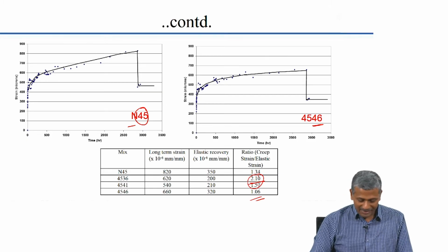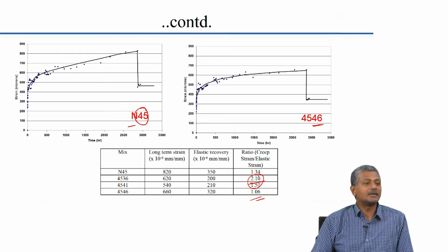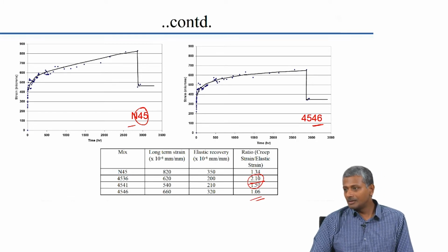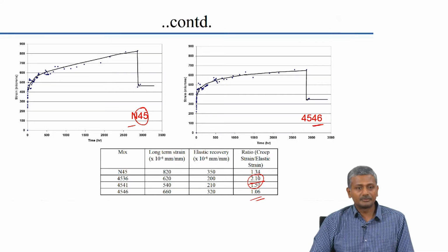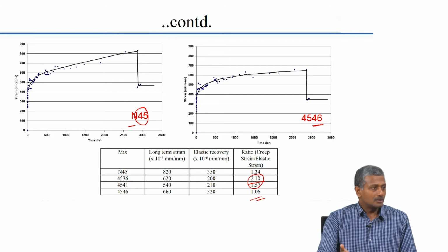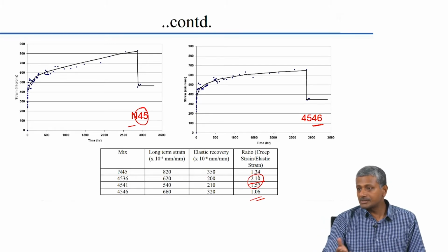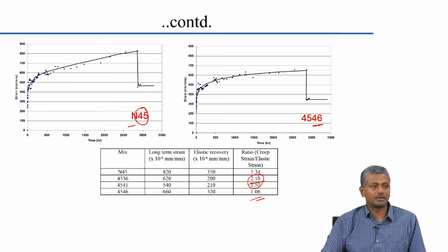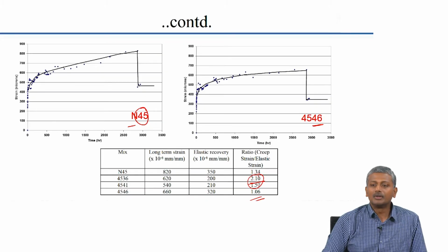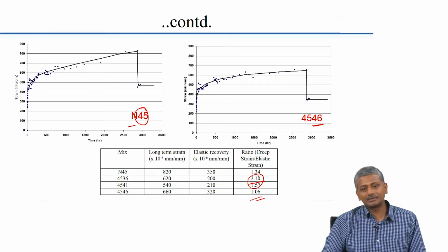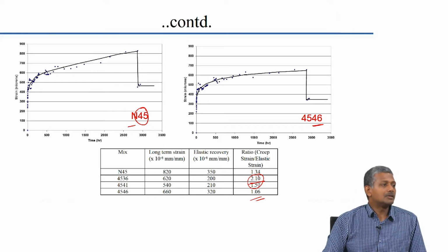Okay. At this stage I think we should understand that concrete mix design, when it is undertaken for a project, needs a substantial amount of time, because it is not just the 28-day compressive strength that we are designing for, it is for long term performance, and that long term performance obviously includes resistance to creep and shrinkage as well as durability aspects of the concrete. Now very often when we do mix designs for construction projects, at least in the Indian scenario, the primary emphasis is just to obtain the workability and the strength. As long as you do that, the project takes in that input and the concreting process is started.